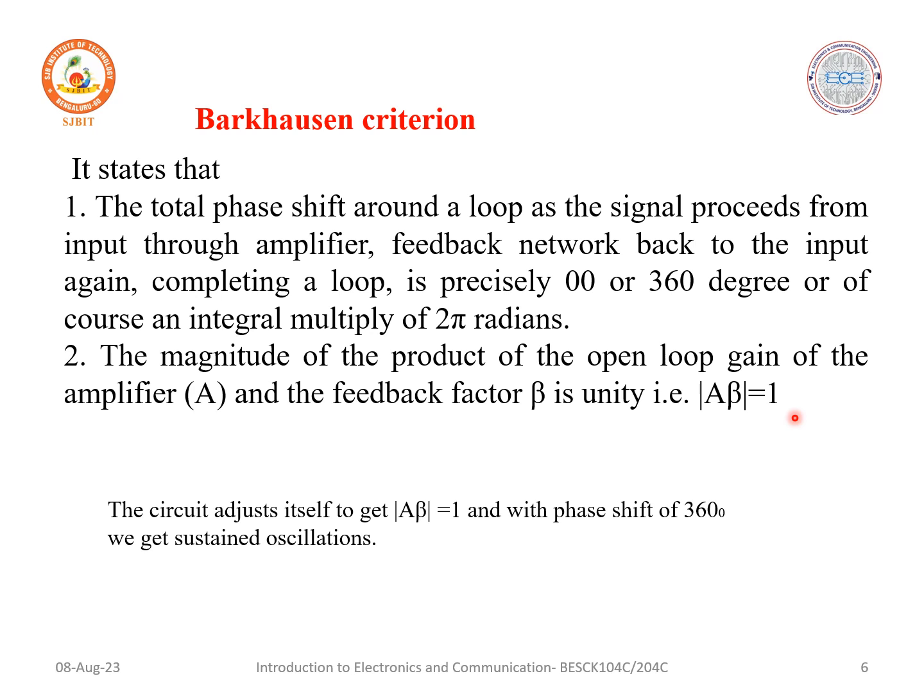The gain of the amplifier should be greater than 1, and beta is the gain of the feedback network. The beta should be less than 1. So to create an oscillator, we need simply an amplifier with a sufficient gain to overcome the losses of the network that produces the positive feedback.